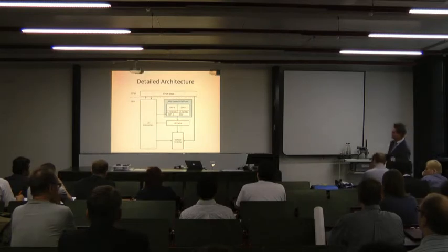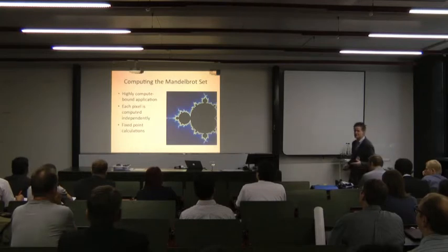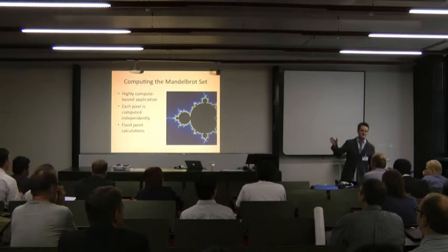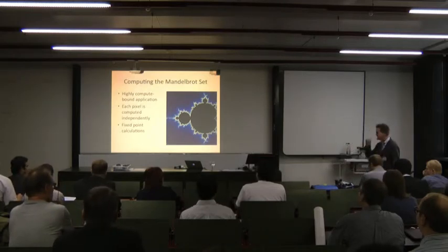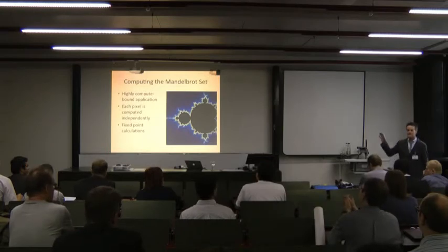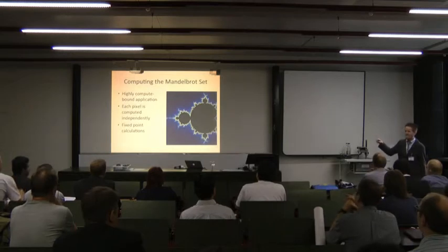Now, it turns out when you have an 800 megahertz ARM processor, it's a lot harder to get speedup versus if you're using a soft-core MIPS, as you might imagine. A soft-core MIPS, say, runs at 80, 90 megahertz versus using an 800 megahertz ARM processor. So the CHStone circuits don't contain many opportunities for loop pipelining. It's very hard to accelerate those over the ARM processor.